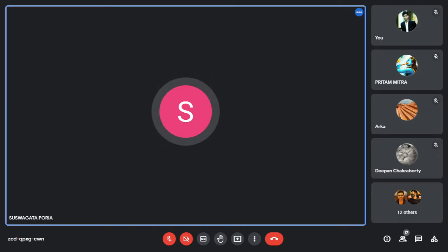When you are giving a diameter, or any length dimension, if it is too small with respect to the letters you have written in your drawing sheet, then that's a very bad practice. When you give the dimension, before or after, you will change the dimension style, the text height and width, its scale ratio, anything. There are a lot of ways by which you can change it. You should change it so that the height of the text in the dimension and the height of the text in the title block are close. They should not be that far apart.